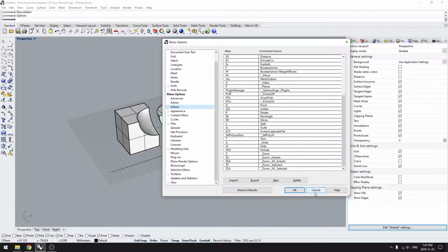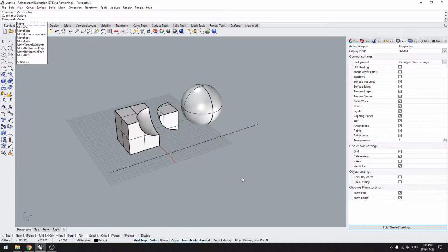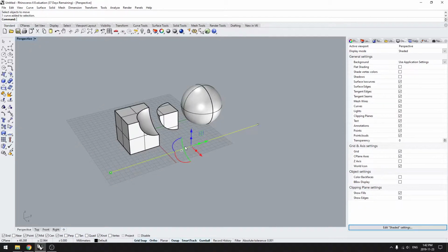Say, I don't know many other languages, but if you're trying to do just move, and you were to send underscore move, and you're running Rhino in another language like Spanish or something, then Rhino would understand that it's the move command. Whereas if you just type move into Spanish Rhino, it's not going to get it. It's going to be like, what is that? That's not the Spanish for move, which I don't know what is, but yeah, that's basically underscore.